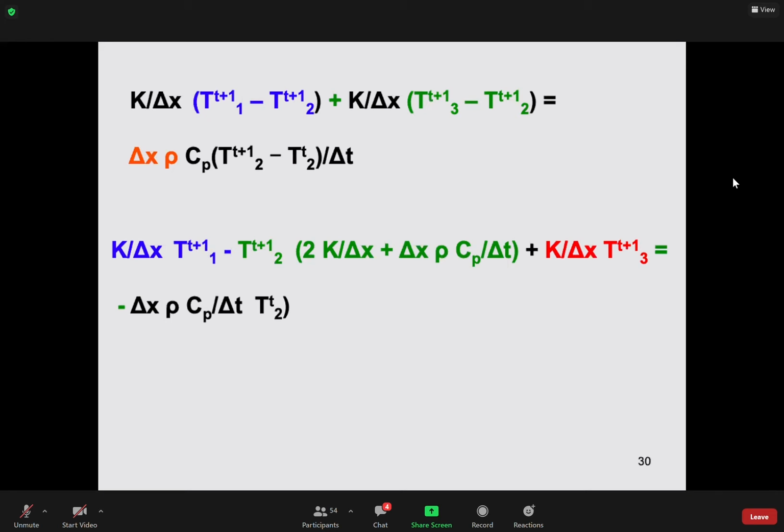So it has to converge within 5%, 10%, or? Yeah, that's a good point. Therefore, what you do here is converge. The question here is, how do you know it has converged? Let me go to the next slide when this gentleman finishes. You select one temperature, one point somewhere in the wall, okay? And compare that temperature today, let's say at 4 o'clock in the afternoon, and then you go to the next day and compare the temperature of that point at 4 o'clock. If the difference between them is less than 0.5 degrees, because of the accuracy of the thermostat, then you can say, okay, I converged, okay?